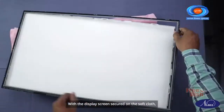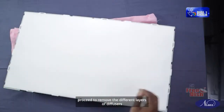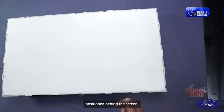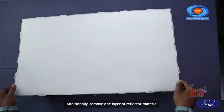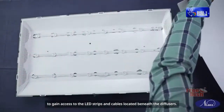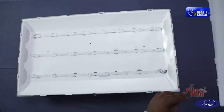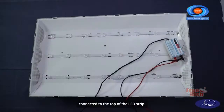With the display screen secured on the soft cloth, proceed to remove the different layers of diffusers positioned behind the screen. Additionally, remove one layer of reflector material to gain access to the LED strips and cables located beneath the diffusers. Finally, carefully unplug the cables connected to the top of the LED strip.